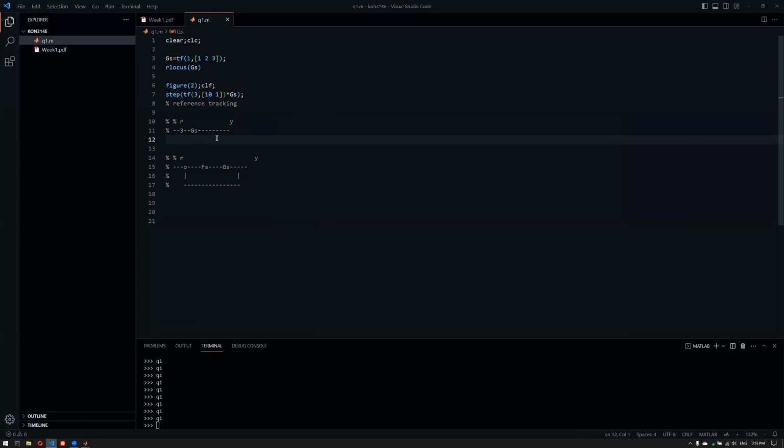That's one of them, which I've done by choosing 3 just by gain, or you can also take the dynamic part here. But the open loop strategy is not that important and common anyway, so we can just get rid of it. It's just to give you an idea, and since we will have disturbance in our systems, this doesn't make that much sense to use, but for very special cases, it's possible to opt for that.